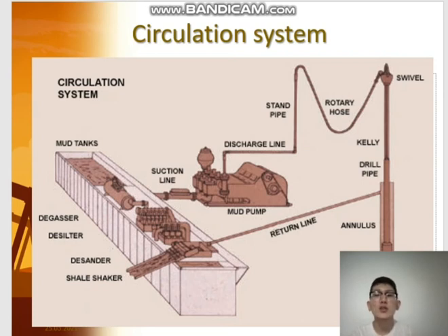I said here we heard about drilling fluid, and I want to say something about drilling fluid. Drilling fluids are subdivided into 3 major classes: water-based mud, oil-based mud, and air-based mud. We know water-based and oil-based muds, and air-based mud is used to reduce bottom hole pressure to avoid circulation losses in surface layers, or we use it to limit damage to productive formations. This is about the circulating system.